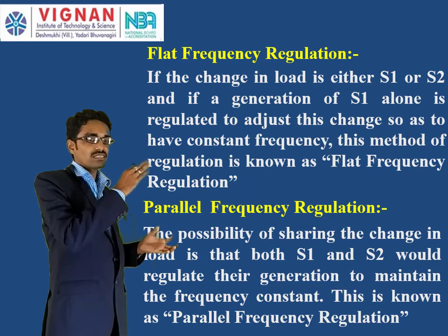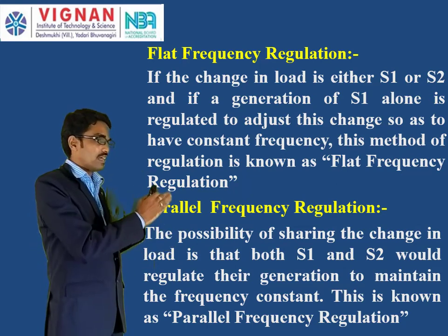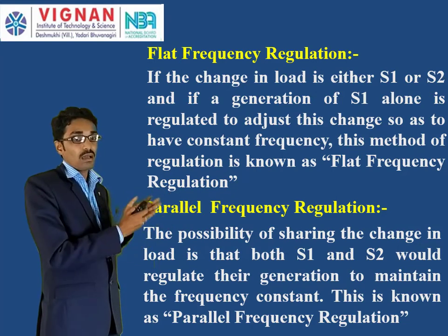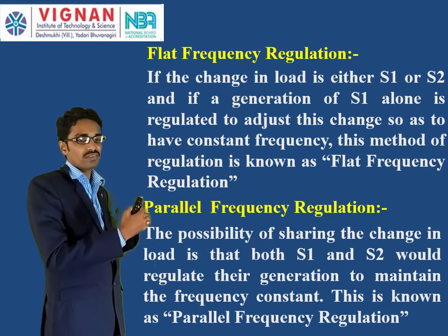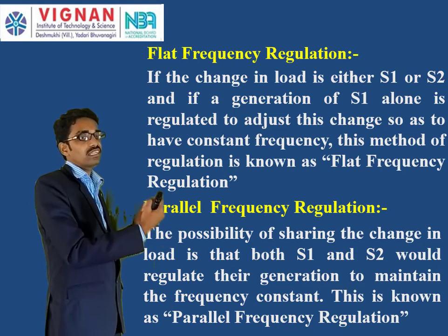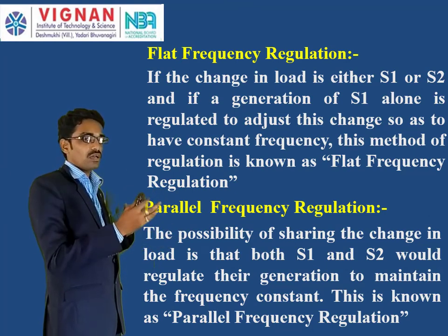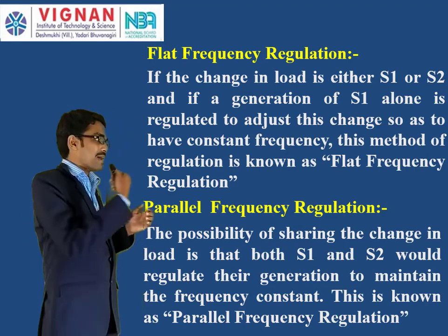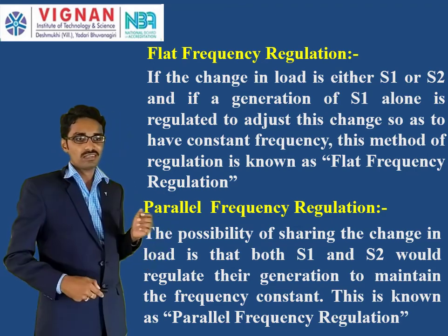But in the previous case, only one generator alone handles the change in the load. Whereas in parallel frequency regulation, both generators change their generation in order to meet the load while maintaining a constant frequency. This is known as parallel frequency regulation.